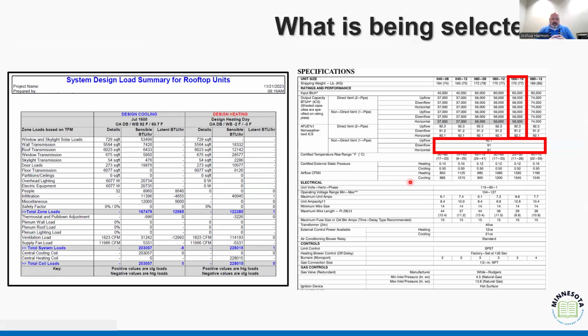But one of the things that's happening in this process is, again, we've identified a load for heating requirements. We've identified a ventilation requirement. Now we're selecting equipment that matches that load. And so if I start to look at that table, we've got these 3 different sizes of equipment that all provide the same level of heating output, right? They all provide the same BTU. What they change is when we start talking about the airflow, right? Our airflow rates change. And so if I'm looking for airflow rates, I'm going to select a different piece of equipment.